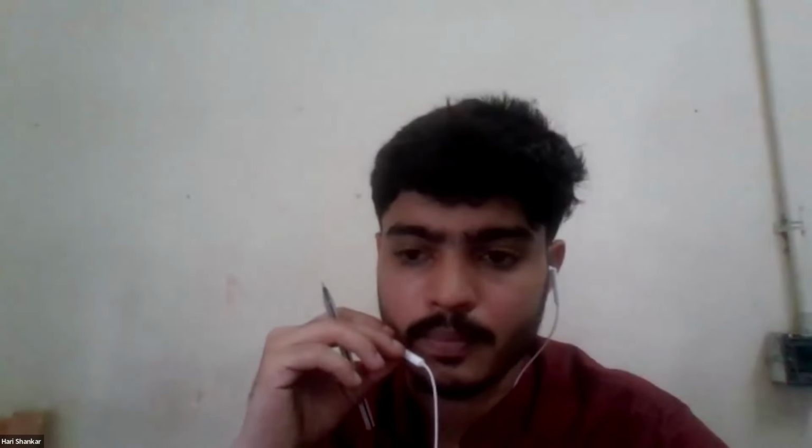X will get updated from 0 to 1 because of the statement delay, and y will not change because it's already scheduled as y equal to 0. So my final answer will be after 10 nanoseconds, x will be 1 and y will be 0.